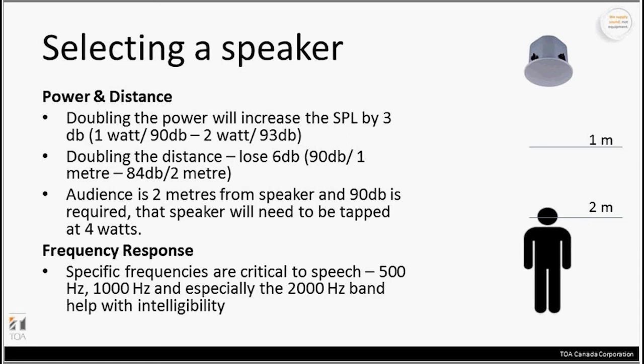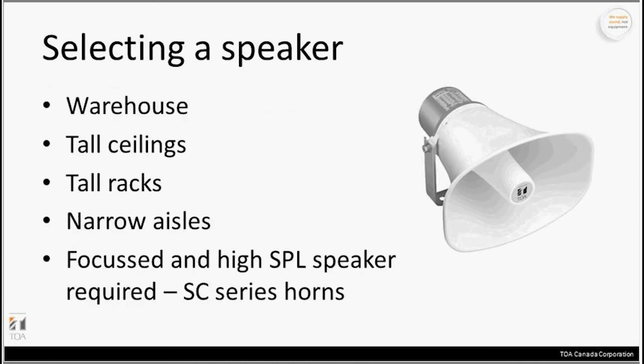Frequency response is also very important when we're looking at speakers. We should remember that specific frequencies are very critical to speech. 500 hertz, 1,000 hertz, but especially the 2,000 hertz band really helps with a lot of the intelligibility issues. So you would want to make sure that the frequency response is appropriate in the speakers that you select. So let's look at a few situations.